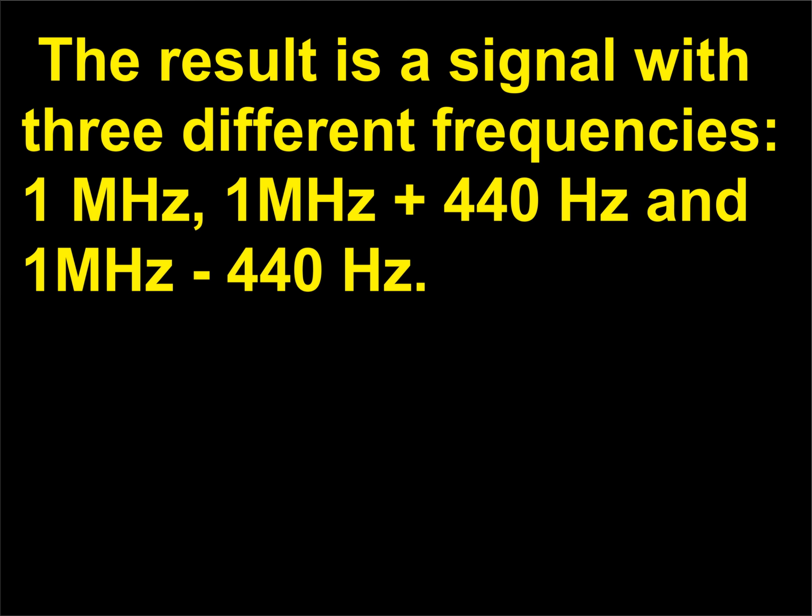Sounds with a frequency of 4 kHz require a range of frequencies, called the bandwidth, 8 kHz wide, just about the spacing between adjacent stations. FM stations, on the other hand, were developed to transmit sounds more faithfully, which means that sounds up to 15 kHz must be accommodated.